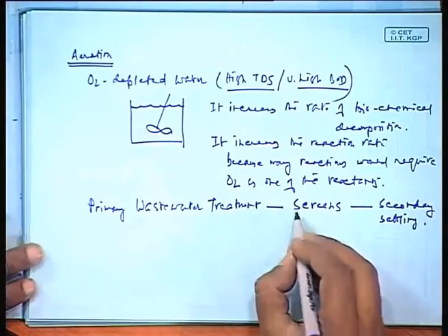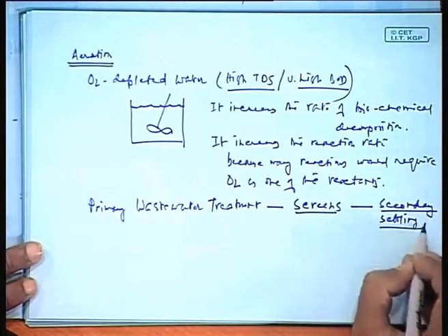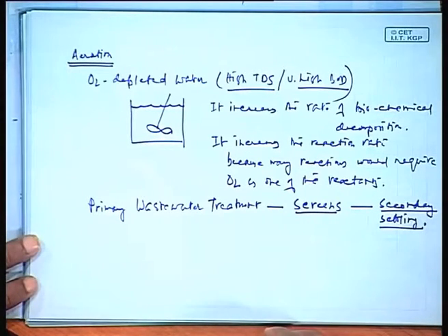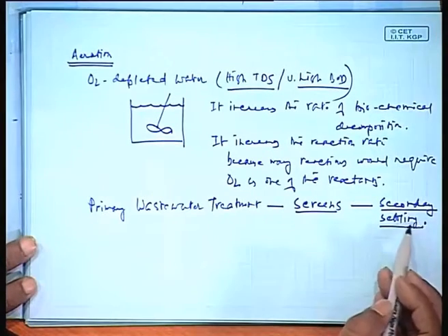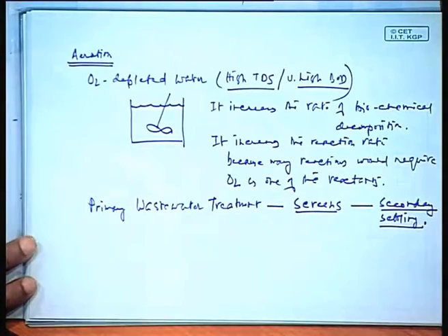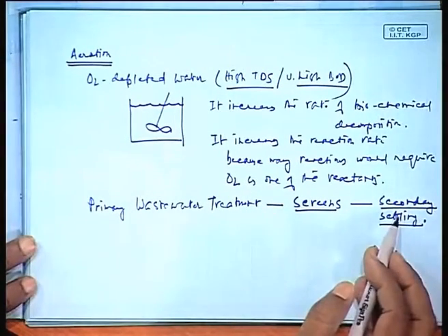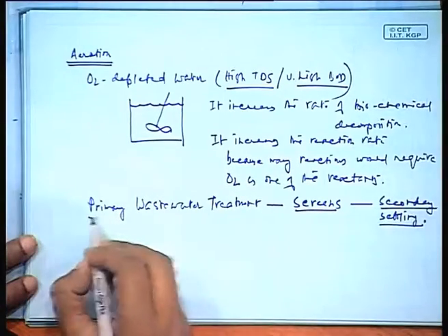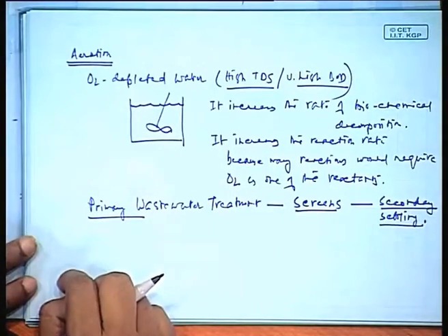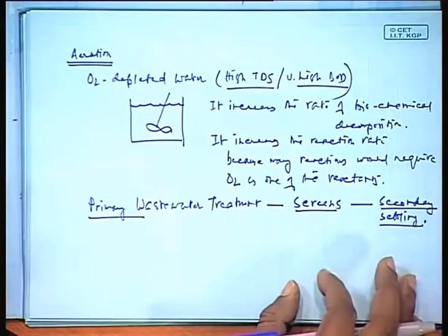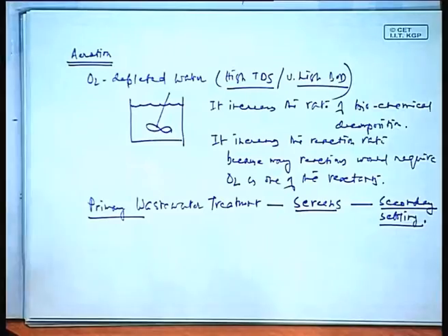In many places, even in places like IIT Kharagpur, the typical wastewater treatment method, if they are not adding any substances, is basically only primary wastewater treatment. In most cases we are not adding anything, we are just allowing the natural reactions to take place. We are trying to facilitate the natural reactions, the substances within the water reacting with each other and finally settling. So this is what is called the primary wastewater treatment.